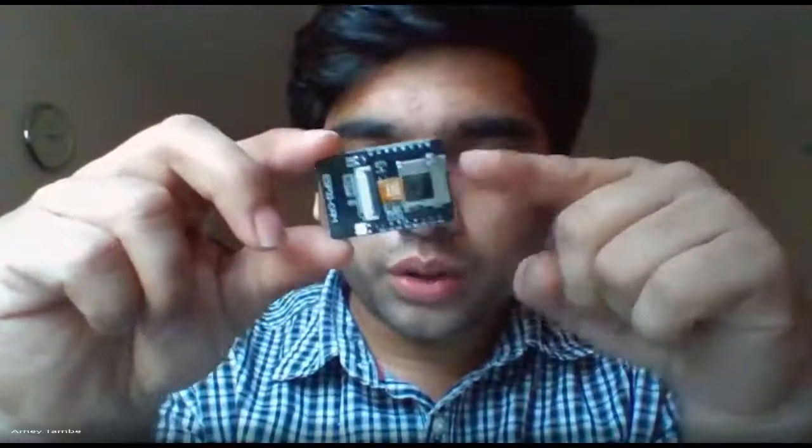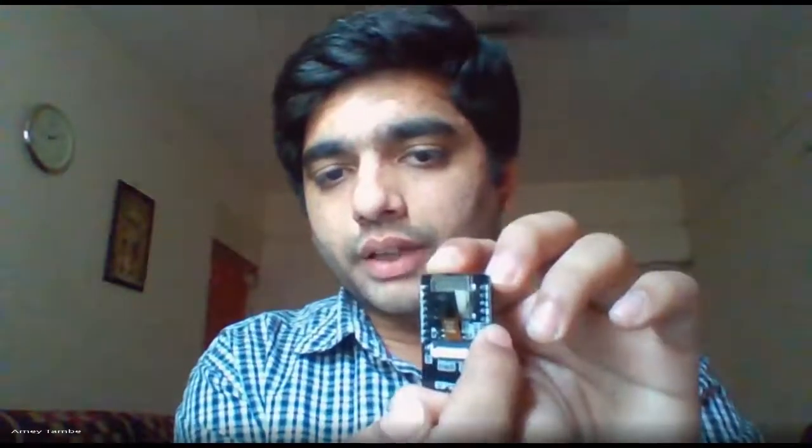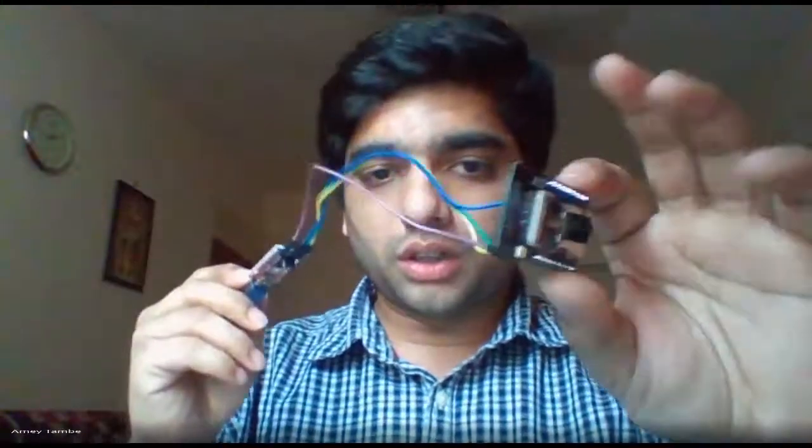So I figured out how exactly this is going to work, because I mistakenly misplaced some wires. That's why it was not working, as I was in a bit of the dark. These wires are very close to each other, and instead of 5 volt, I connected VCC to VCC. So here on our TTL converter, there is a VCC pin, and that's supposed to go to 5 volt